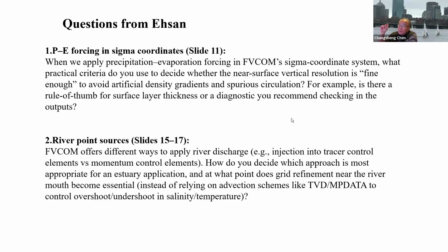One: put a river, make sure you get a river channel into the land. The second suggestion: when river discharge is larger, either way is fine, but when the river discharge is very small, don't use node input. We also found it very interesting when we did the Changjiang River. If we use node input in the Changjiang, even if we get a channel into the Changjiang, we find the fresh water comes down very slowly.